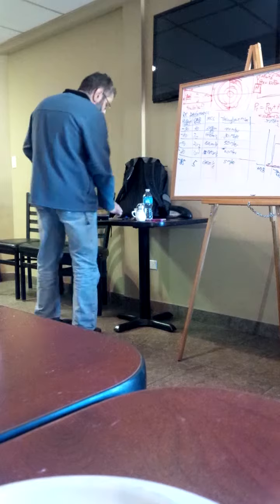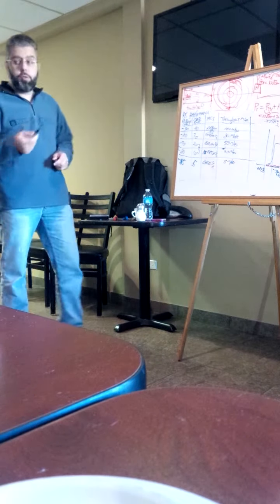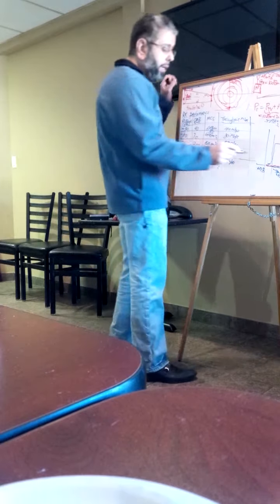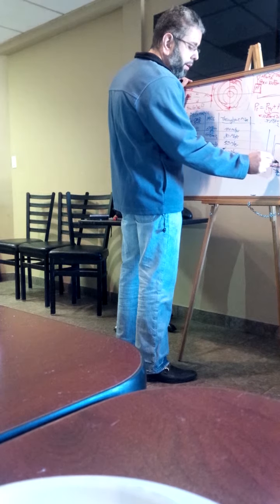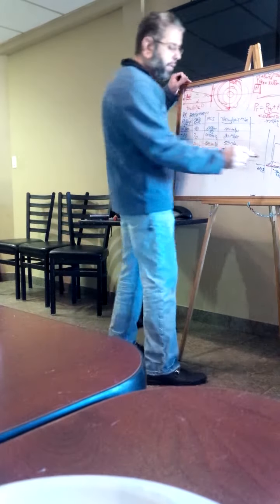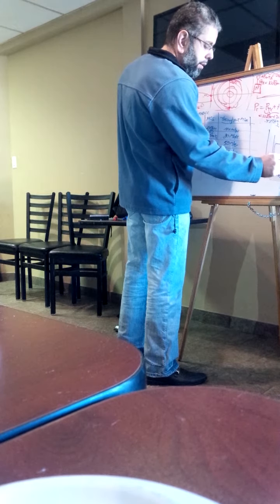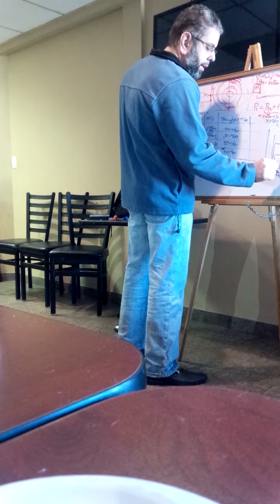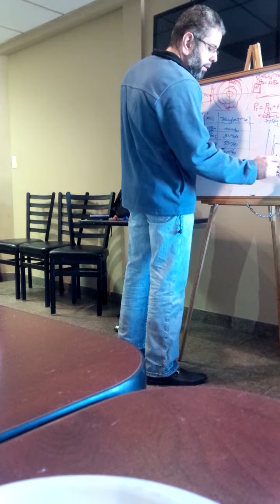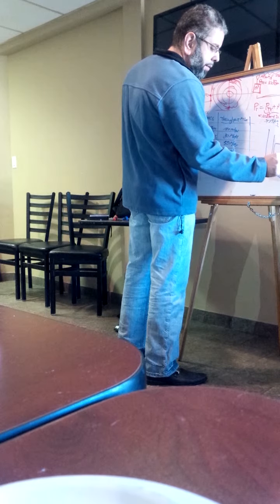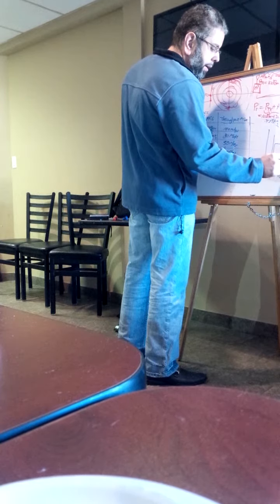But let's say that somehow now someone else is transmitting on my same channel, and he introduces some interference here for me. So let's make him higher to make a bigger problem. Someone else is transmitting on my channel, and let's say that he comes in at minus 70 dBm. This is my interference.